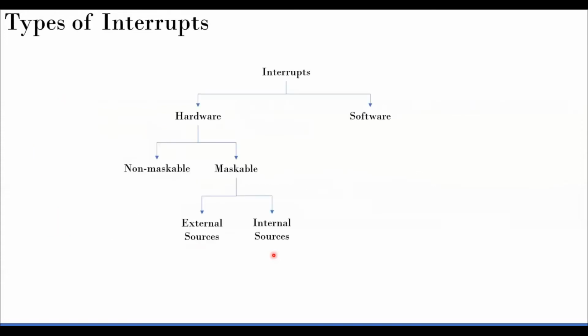Okay, so moving on, there are many types of interrupts possible, of course, in a microprocessor system. You can see over here, there are some which are actually based on software alone. One classic example is when you try to access an area in the memory which is not accessible. It immediately triggers what is known as a hard fault.